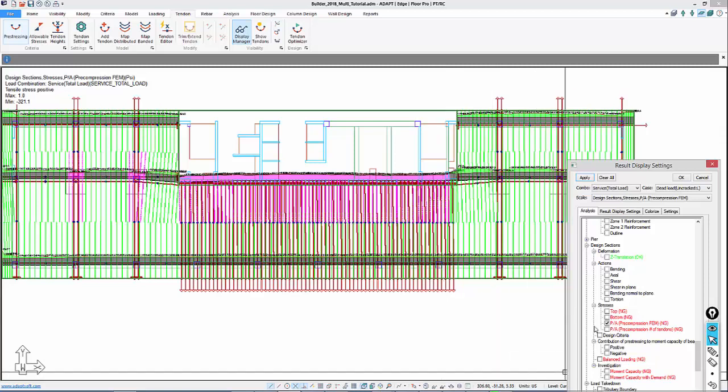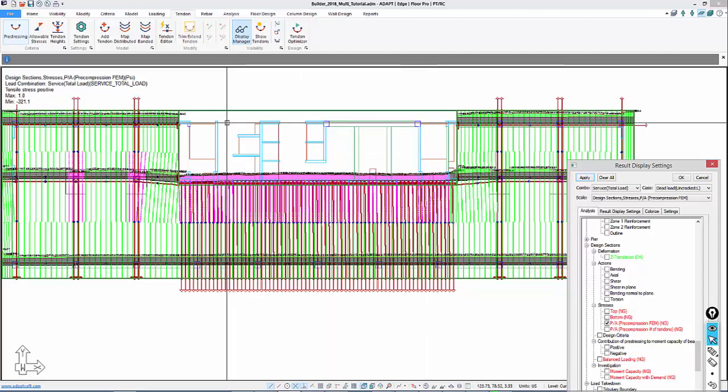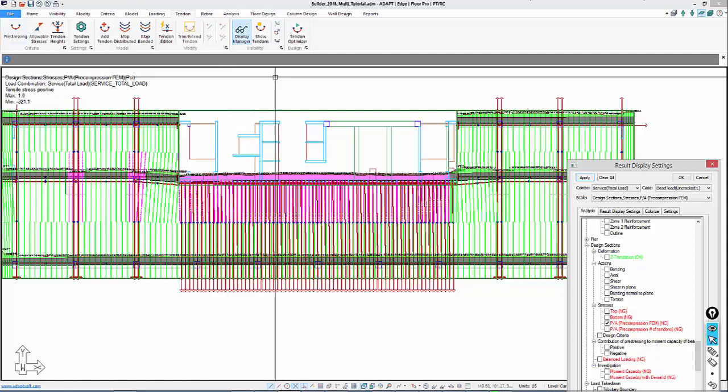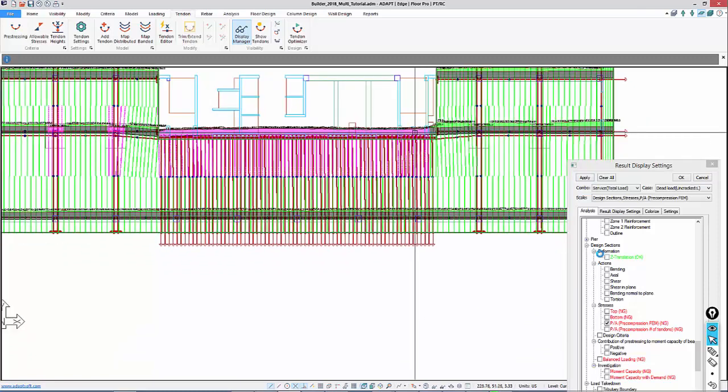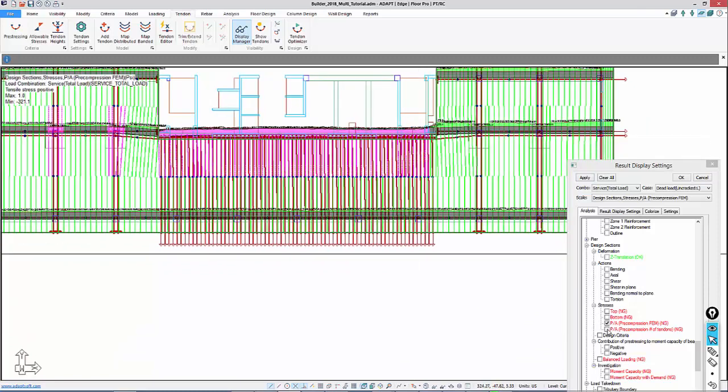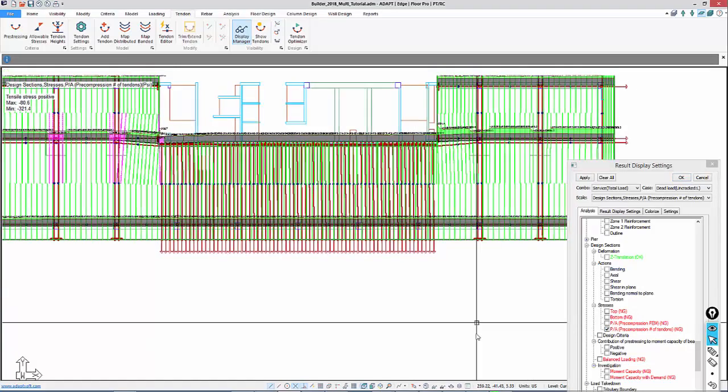So if you're going to use this FEM option, you need to make sure that the wall-to-slab connections and the support conditions allow for the slab to shorten freely so that it mimics, again, real life conditions for the transfer condition of the force into the slab for the PT. A lot of times you're going to use this number of tendons option just as a bypass, knowing that you're going to detail it, allowing it to shorten freely. So that's what the two different options are. For stresses,